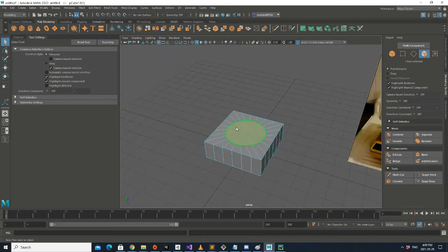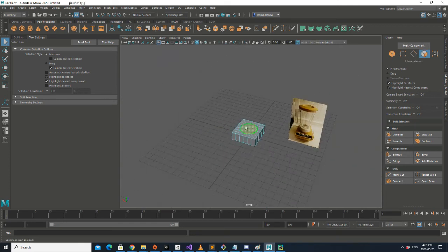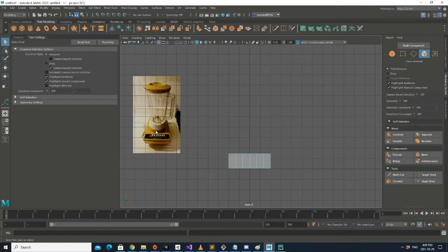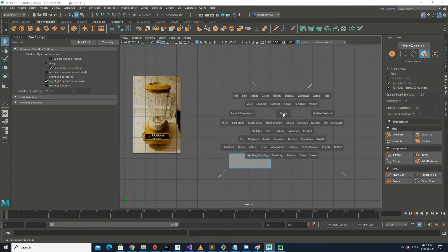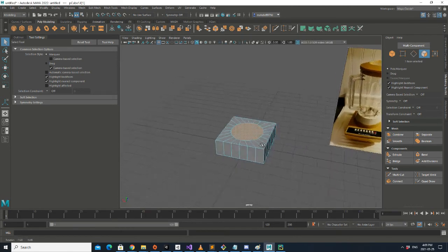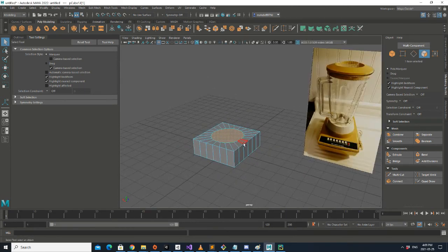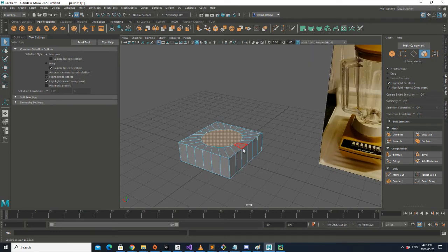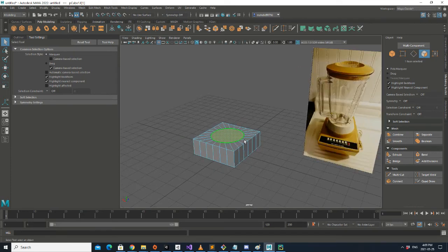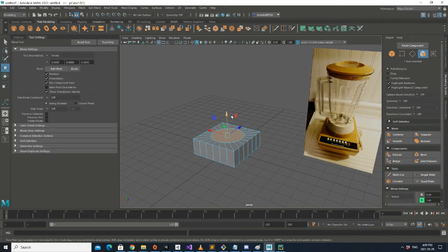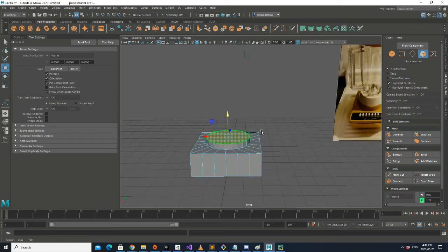Now I can work with this circle here and make a very good looking cylinder coming out of my cube. So again, let's just go with extrude. There are many ways you can do it, as I said: hold shift and move the cylinder up.